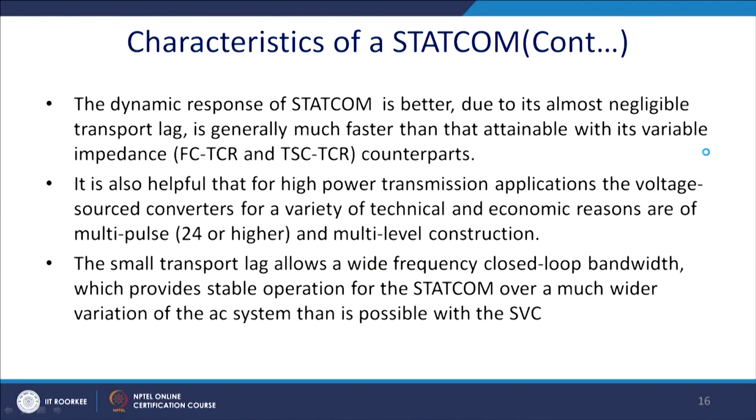Now, the dynamic response of the Statcom is better compared to SVC. Why? Due to almost negligible transport loss or transport lag. Generally, it is much faster than that attainable with the variable impedance, because a capacitor will have its own inertia, and we also know that we want to have a transient free operation that we have discussed. So, we have a specific time of switching. Here you can change this dynamics by changing the modulation index of the PWM, and thus it is quite fast.